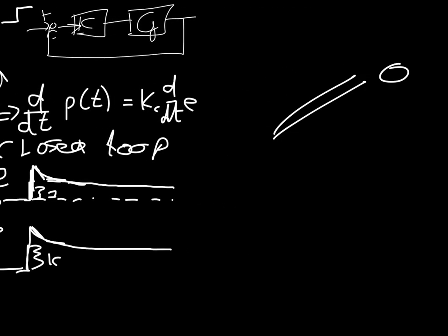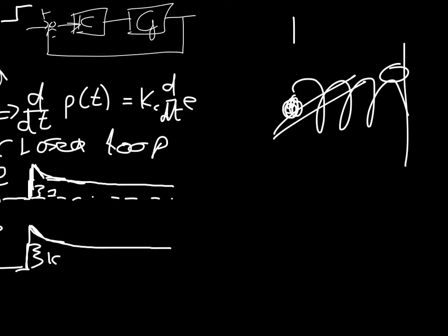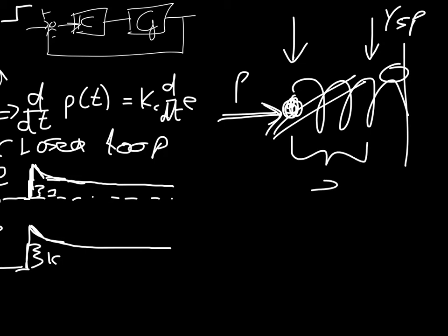An interesting way of thinking about this is, let's say we have something like a spring where the system is pushing back against us. So let's say we've got a spring at a particular position at time 0, and we're trying to move it to this set point. If we push with a force that is equal to the proportional output, then we can easily see that if we start pushing and we push less, because remember this difference is the error, if we push less as the error reduces, eventually we will even out somewhere in the middle.